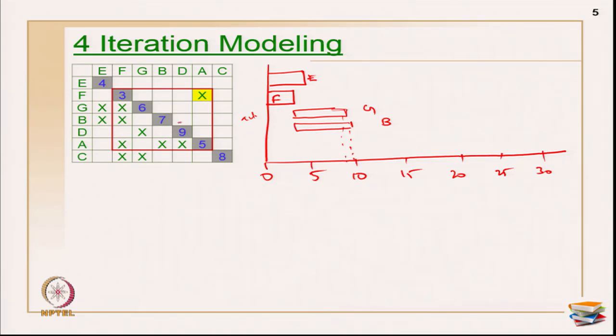Okay. The next activity B and D are again parallel. For example, activity B is dependent on. So, after activity B I have to do my activity D, okay. So, now activity D I am getting inputs for activity D only from G. So, after G I can start my activity D, and it takes 9 days of duration, okay. So, 9 plus 7 is somewhere around 16. So, this is primarily my activity D, stopping at 16.